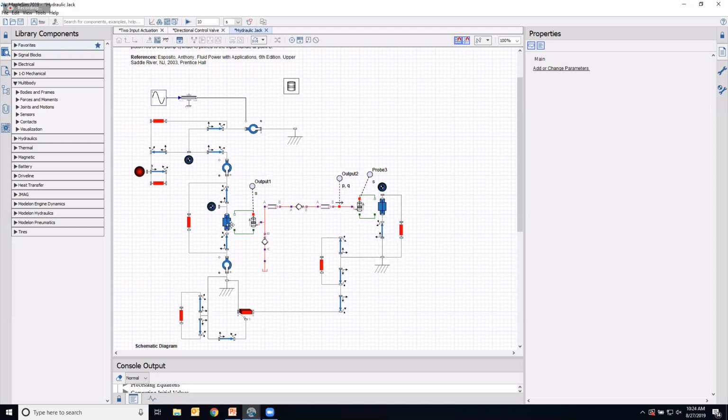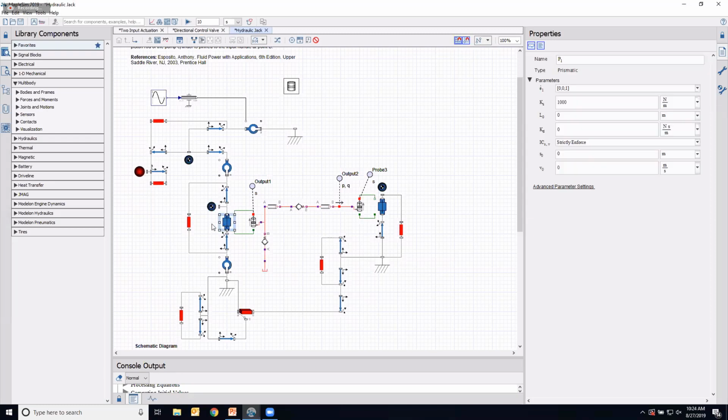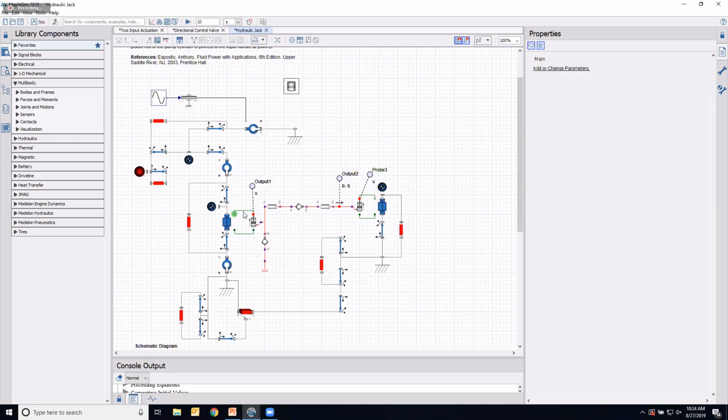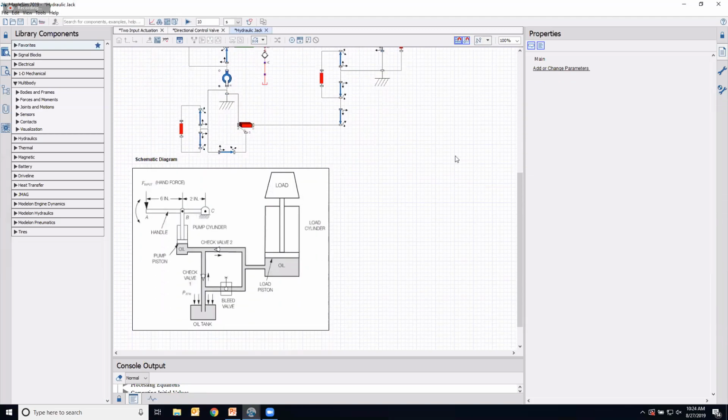and then I'm able to connect between this multi-body domain, this 1D translational, which are my green lines, and then into my hydraulics. So what I'm trying to model here, and there's a small schematic, is, I have a handle, it's attached to some rotating base, and as I move the arm up and down, I'm using this hydraulic system to actually push up some load.